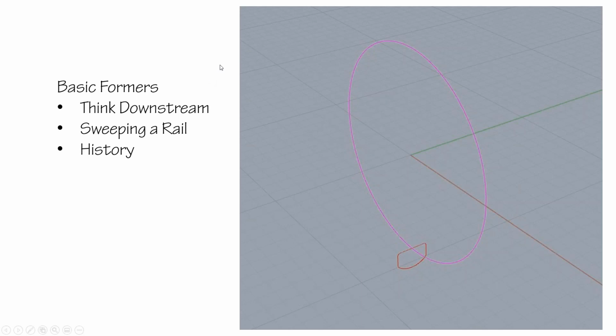Manufacturing consciousness is sort of the little tagline I have on my website. And the idea is that if your piece is going to be cast, as most things in the jewelry industry are today, then you have to think about that process as you're doing your design. What's casting friendly, what won't work, what will work.